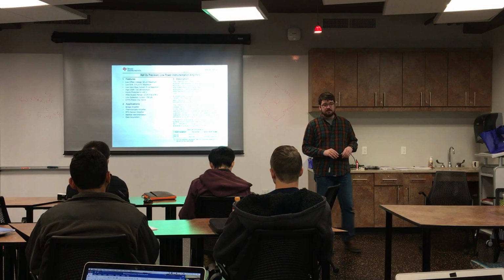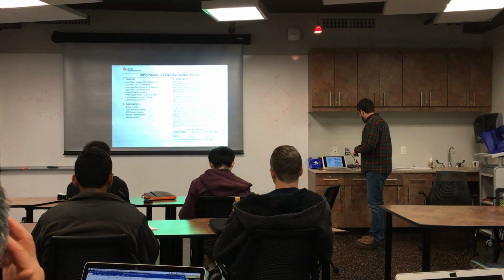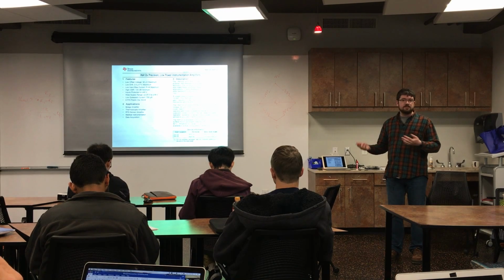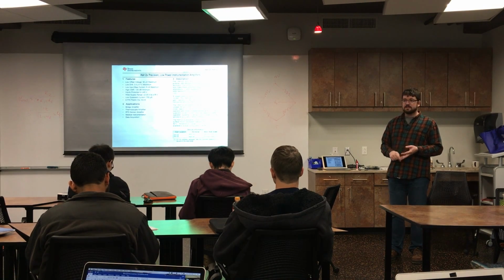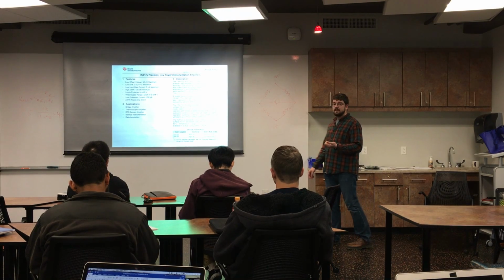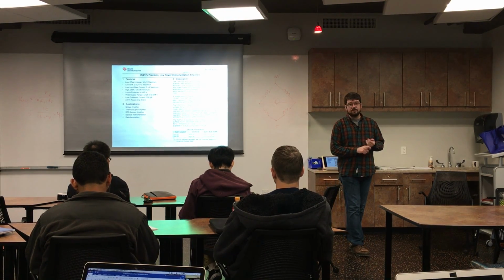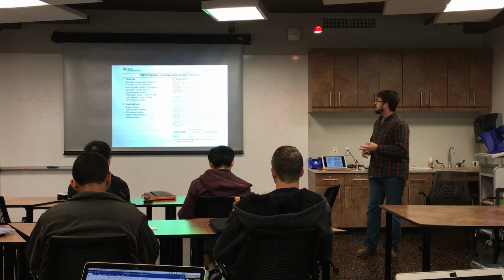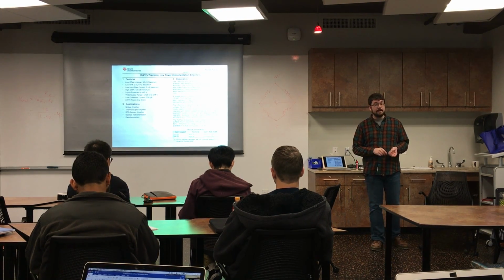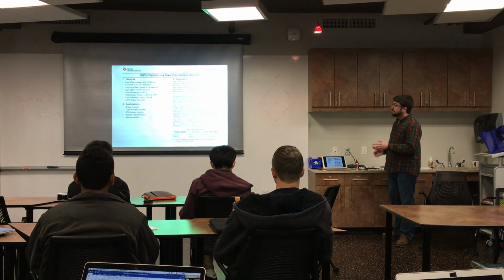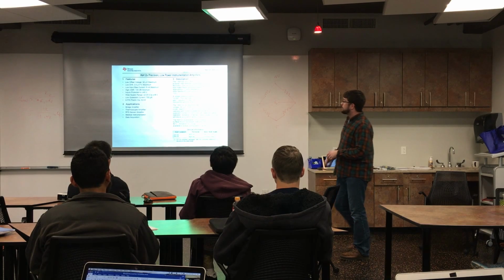One of the amplifiers that's my favorite, there's a lot out there. Analog Devices has a series of them, the AD600 series, so the AD620, 630, 680. Texas Instruments has their INA series for instrumentation amp. The INA105 was a really, really common part, and they still make it. They've upgraded it now with the INA128 and 129. And I've got some INA128s that you're going to use on Thursday.